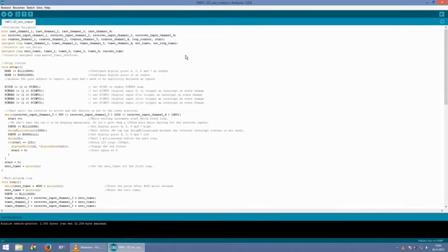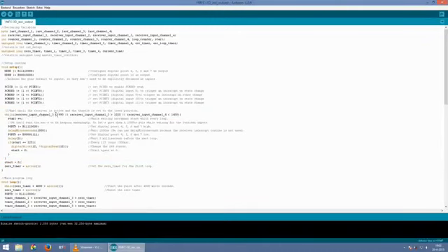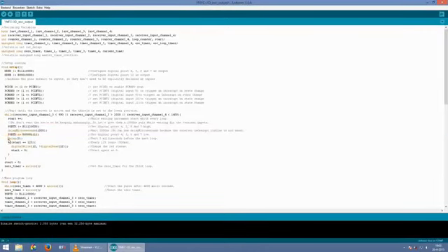Now this is the final program that I wrote for this video. I'll put a link in the description. Most parts are already discussed. This new part, however, is to make sure that the receiver signals are active and that the throttle is in the lowest position. If this is not the case, the main program will not start for safety reasons. To prevent the ESCs from beeping annoyingly, they are fed with a 1000 microsecond pulse at 250 Hz. And for the visualization, the LED state is changed every 500 milliseconds.